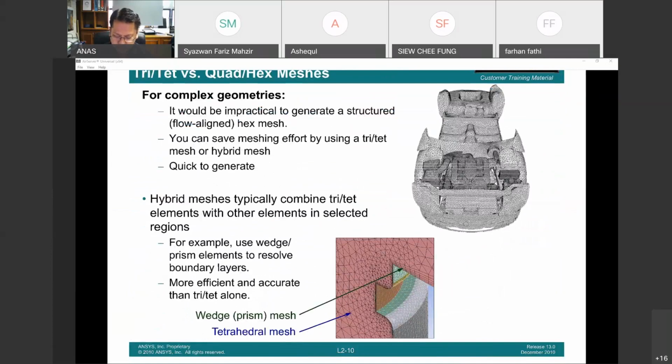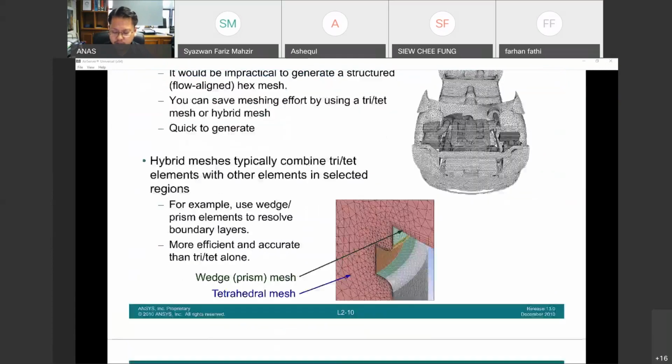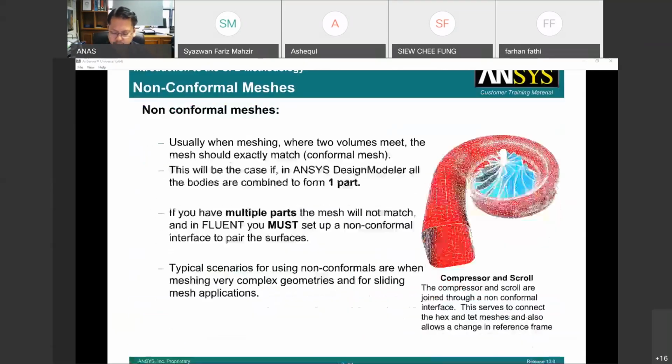Right. So what else? So we discussed before, basically, we have several options in meshing. We have global, we have localized meshing. We also can use a mix of structured and unstructured. Maybe you can use curvilinear. So be creative. For complex shapes, sometimes or most of the time you need to use the unstructured. But if you have a mix of complex and simple shapes, try to mix them if possible. Okay, all right. So this is the issue that we discussed before.